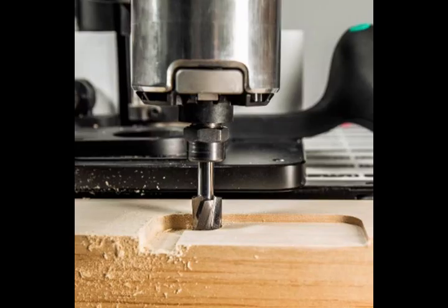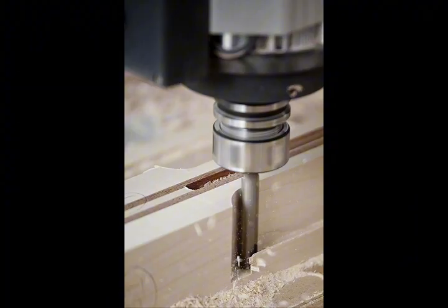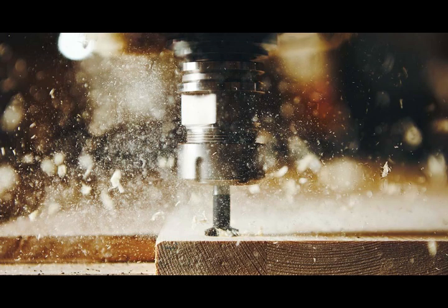Plunge rate. Plunge rate controls how quickly the cutting tool enters the material vertically. Because the cutter has less room to evacuate chips during vertical movement, plunge rates are usually much slower than horizontal feed rates. Reducing plunge speed helps protect the cutting edges and prevents unnecessary stress on the spindle.